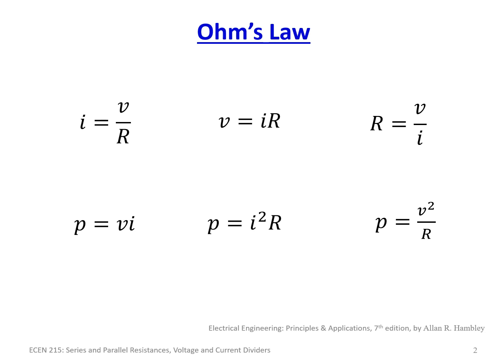It's also important whenever there's a question regarding power, which is in units of watts, that you maintain the concept that power is the voltage times the current. Or it can be written as I squared R, which is the square of the current times resistance. You can get to that equation by looking at V is equal to IR. Since power is voltage times current, it'd be I times IR, which is where you get the I squared from. And power is also V squared over R, since current is simply V over R, hence the V squared.